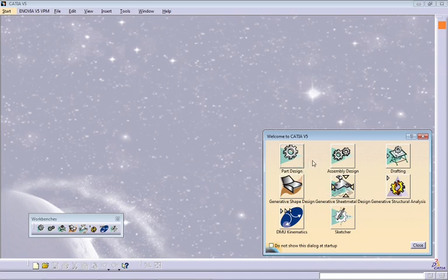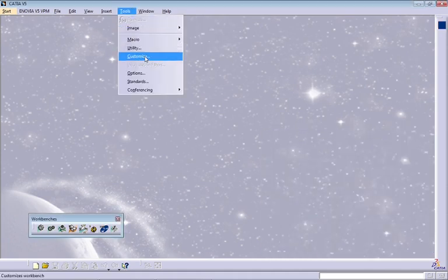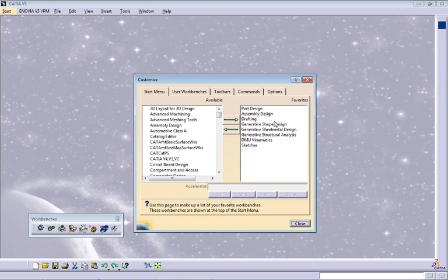But I do not like this order. I want to change it. How can we do that? Well, I don't know which version of CATIA V5 you're using, but if you have a window just like mine, I would suggest you select and hold the left button and move the text of the workbench, just like I did here. Okay: Sketcher, Part Design, Drafting, and Assembly. The rest, I don't care. So just leave it, if you're going to change, okay.